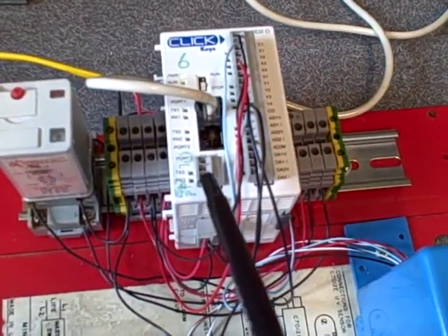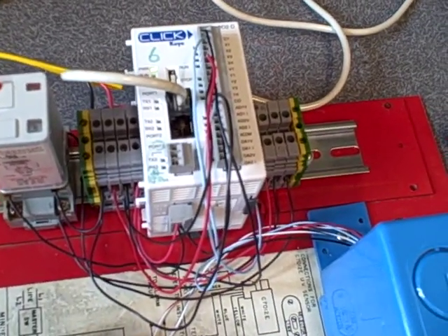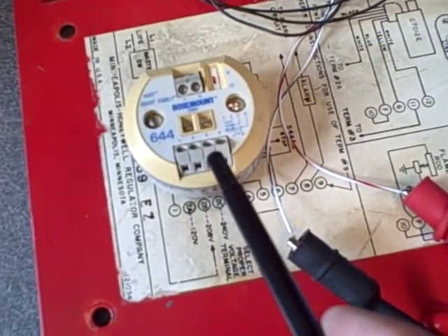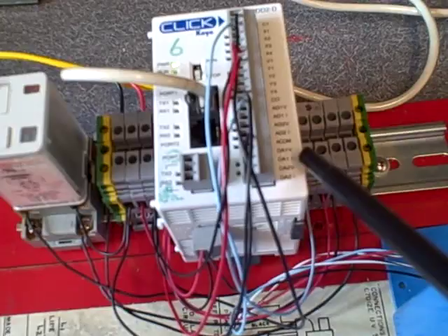We're going to configure the analog input channel of the PLC so it properly measures in the temperature range we want. Our desired temperature range is 0 to 500 degrees Fahrenheit. So we want to scale the input here so that 0.6 to 3 volts registers as 0 to 500. So here we go over here.